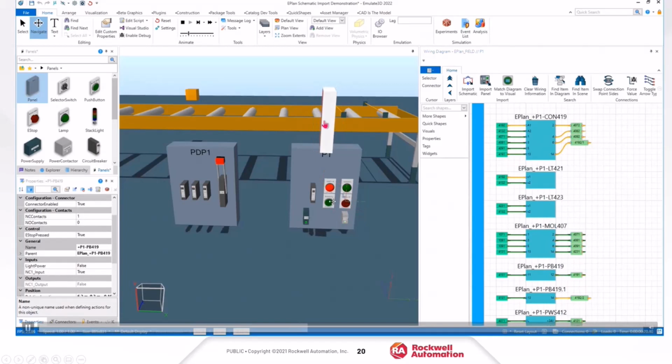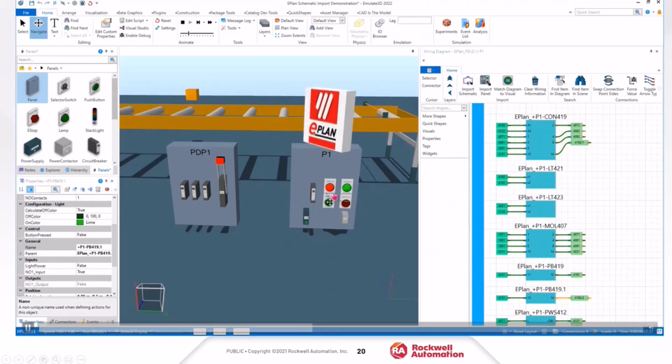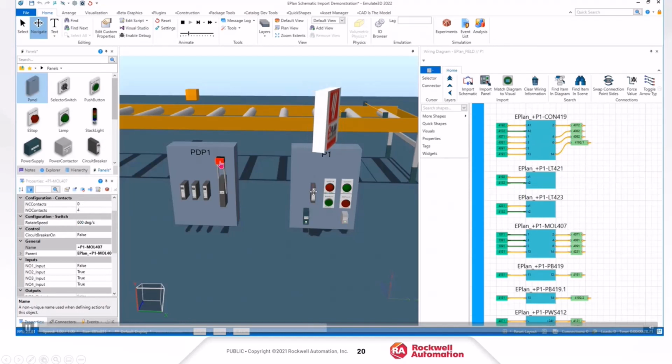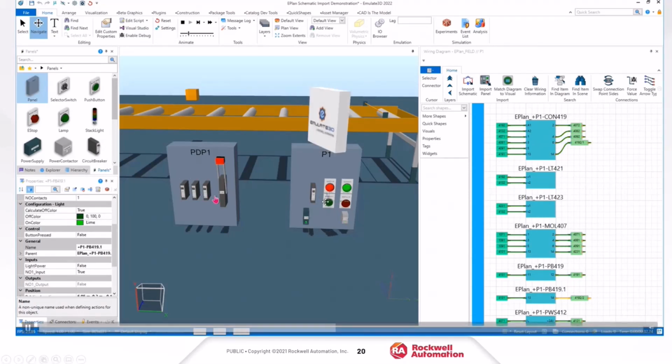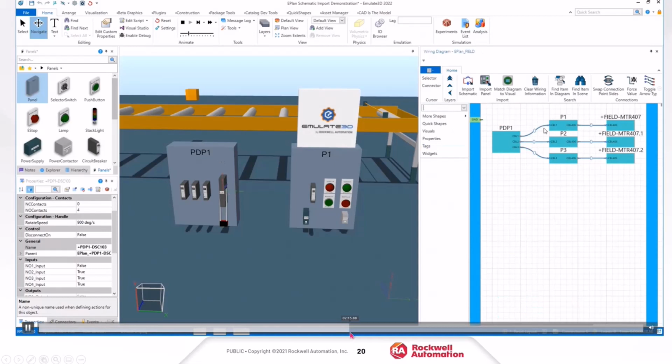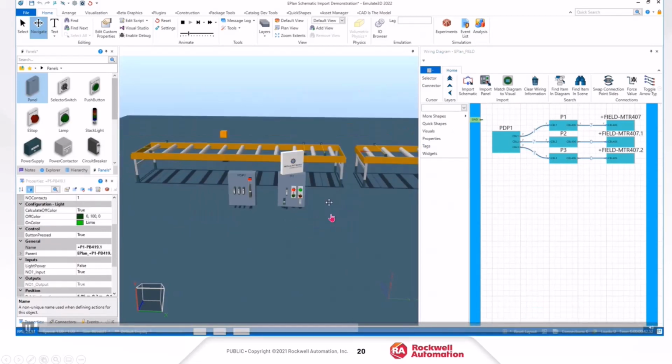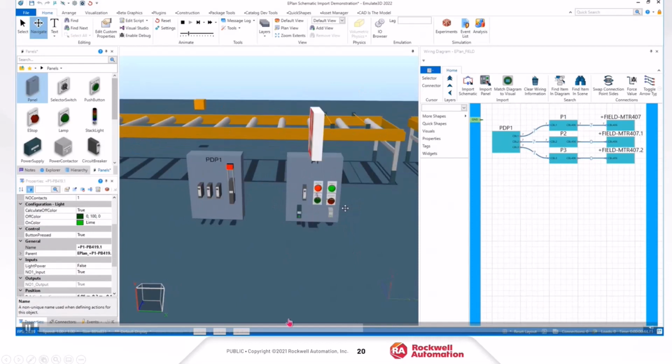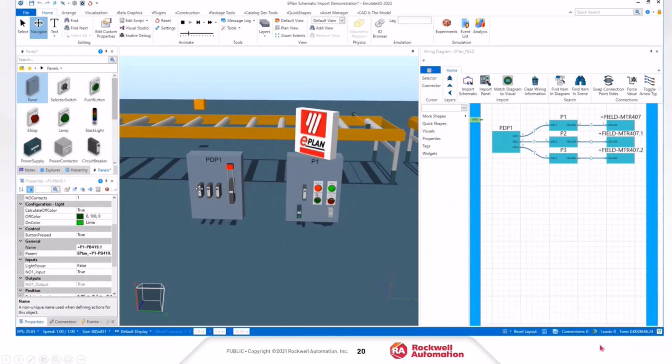The motor stops. One of the benefits here is now you can validate power supplies too. So if you shut down the main power, are all the motors going to shut off? If you shut this circuit breaker, is it going to shut down the entire line, or what is going to turn off? So it's really cool to see how you can validate the wiring diagrams from EPLAN inside of that 3D model.